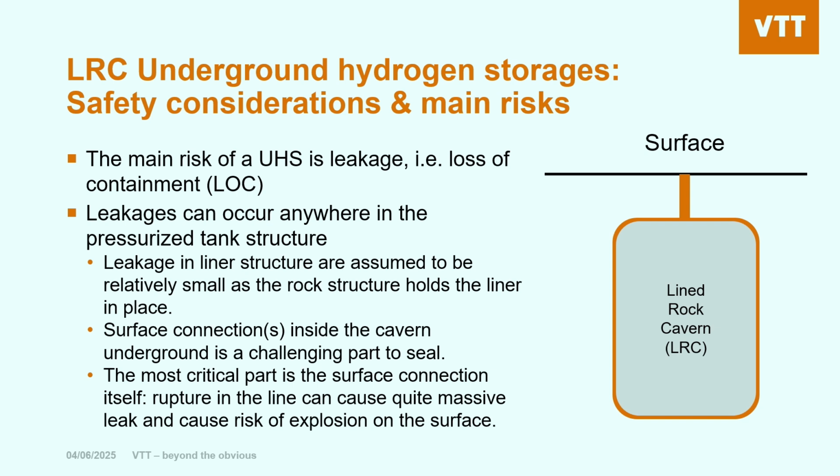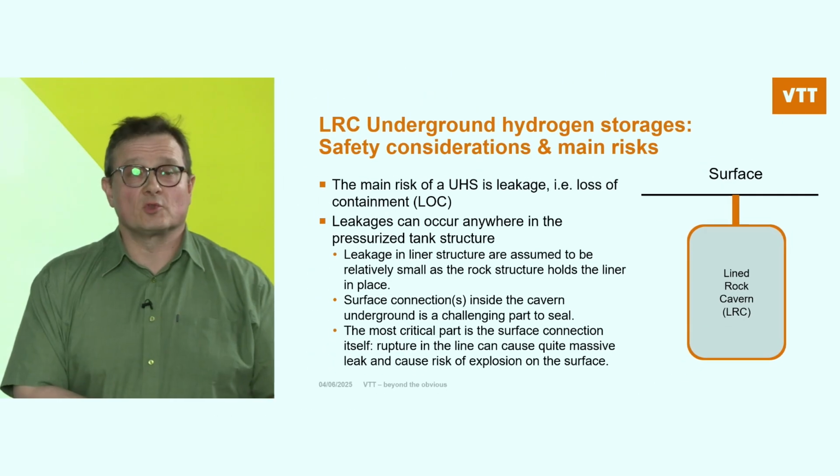But the weakest spot is probably the surface connection in the cavern. But if we are talking about the most critical part, it is the surface connection as a pipeline, because in that line there could be a really massive release of hydrogen, which can, of course, lead to an explosion on the surface.